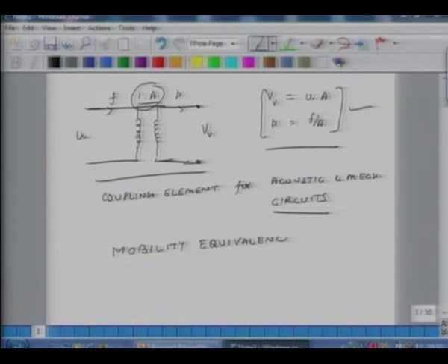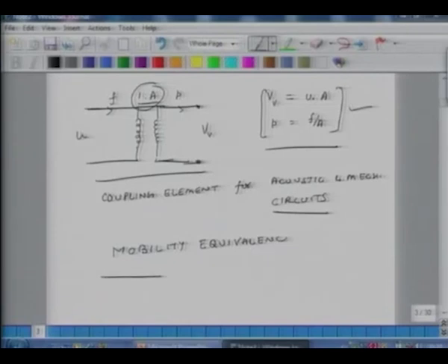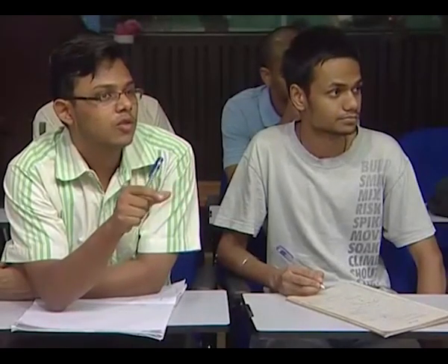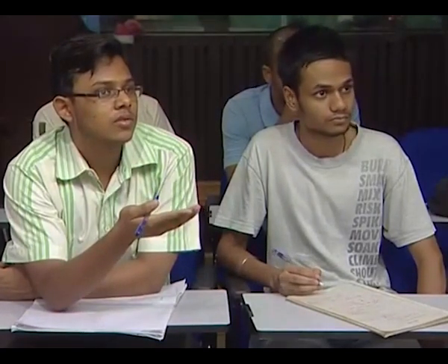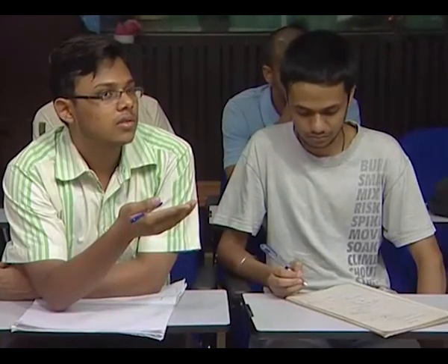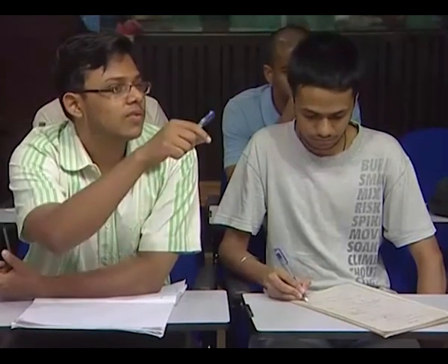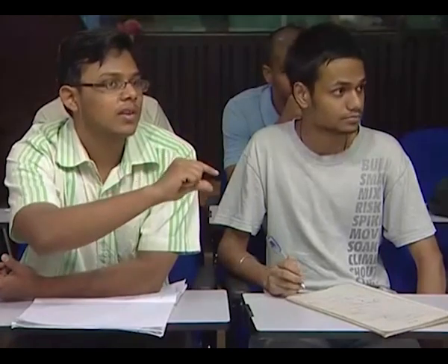So this is the last piece in the whole puzzle. So now we know how to construct an electrical circuit. So I can have an electrical impedance, and then I can have a transformer. Now we are just interchanging the through variable and across variable, so the turn ratio becomes inverted. When you do the actual math, you will see that it becomes A:1 instead of 1:A. So F will always be P times A.